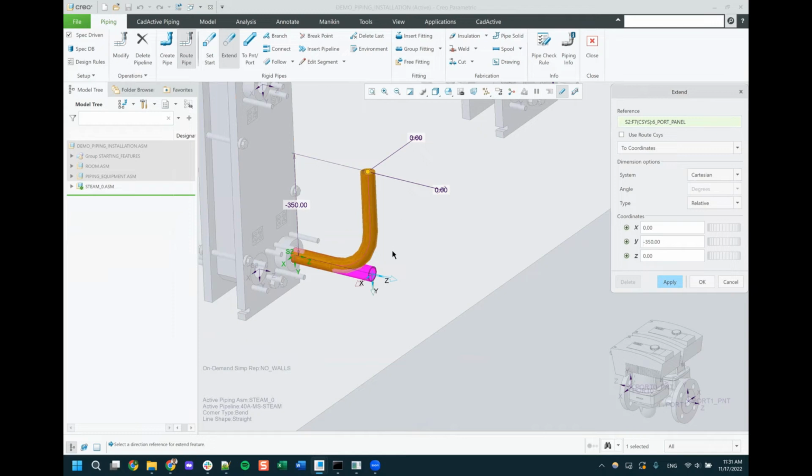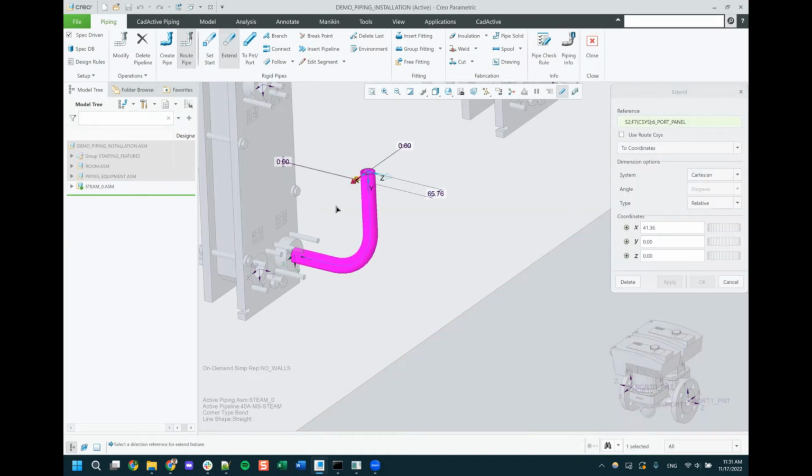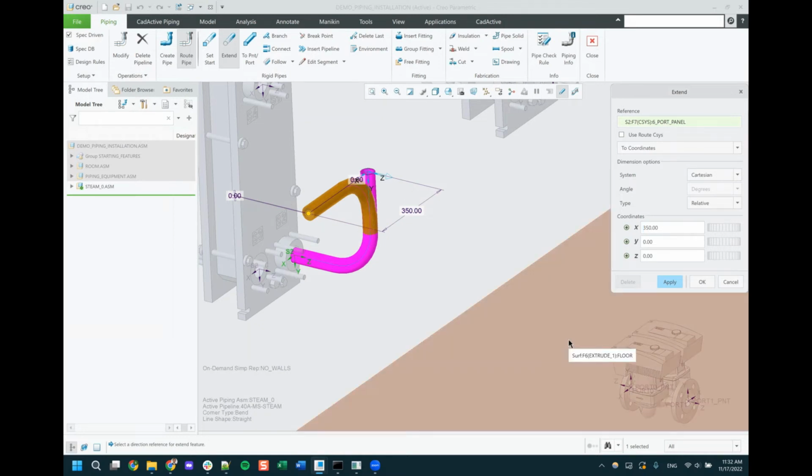If that was not the case, if we did not have these bend rules set up, then at each of these corners that are created by the pipe, it would really just run one pipe all the way up to that corner and then become disjointed and have the other pipe run from that corner up to the next dimension. And from that point, there are some really easy ways to just say, I want to replace every corner with an elbow fitting, and it'll snap into place.